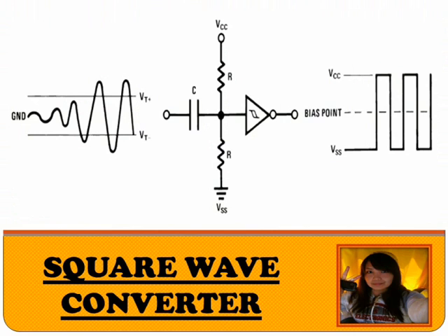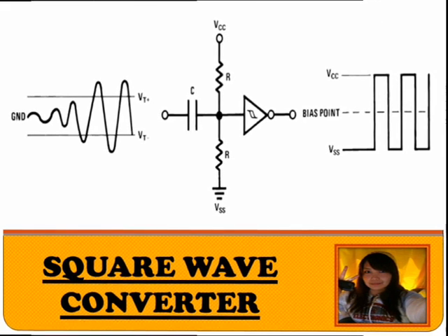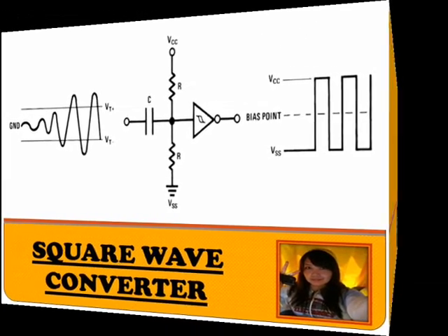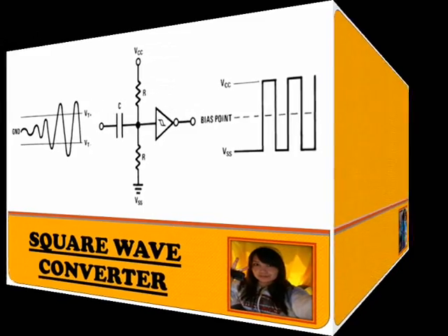Because of input symmetry, the Schmitt trigger is easily biased to achieve 50% duty cycle. The high input impedance simplifies the selection of the biasing resistor and coupling capacitor. Since CMOS has a wide supply range, the Schmitt trigger could be powered from split supplies. This biases the mean threshold value around 0 and makes direct coupling from an up and down output possible.